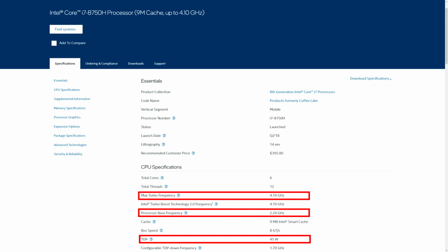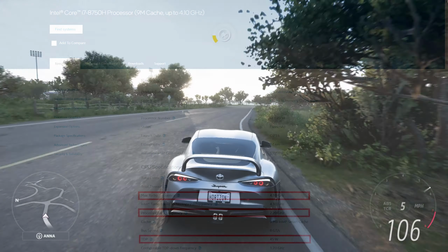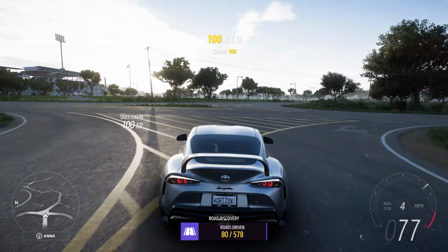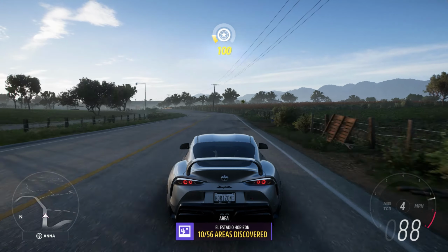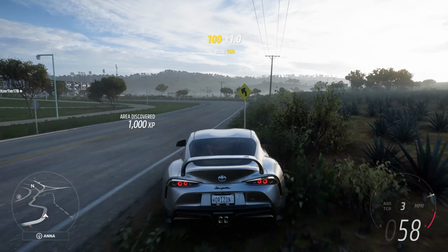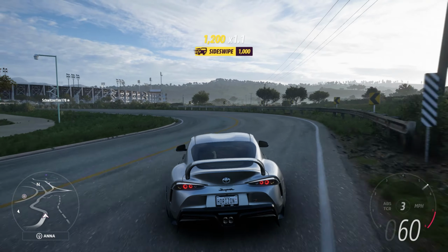And the last one is max turbo frequency. Generally, it's different for single-core and multi-core mode. It represents a maximum frequency the CPU can achieve when certain conditions are met. For example, your CPU should not go beyond the TDP, thermal and power consumption limits. Why does the same CPU work differently in different laptops? There are two main reasons. The first is simple. Base CPU specification can be modified by the vendor, I mean your laptop manufacturer, and also throttling, that can affect your CPU performance in order to reduce heat and power consumption.